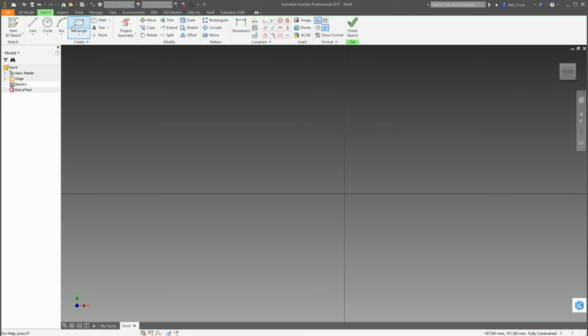So let's delete that, and then let's wrap this up by looking at how to show and hide constraints. This button here on the sketch panel bar is called Show Constraints, and what you can do is just select any line and it will show and display the constraints. When you press escape, it'll keep those glyphs enabled on that object so you can visibly see what constraints are being applied against that line, because quite often you'll lose track of what constraints you've applied and what's been automatically applied, and you need to keep a track of that by visibly seeing the glyphs, so you can then say, right, well actually I didn't want those two lines to be parallel with each other, so let's get rid of that line. And that will now allow us to be a bit more flexible with how we create the sketch.